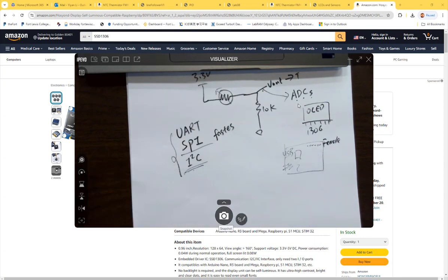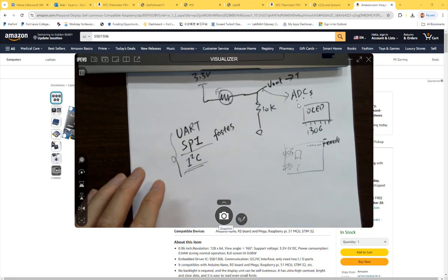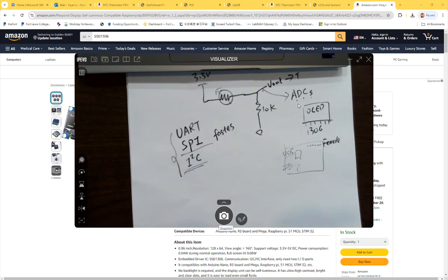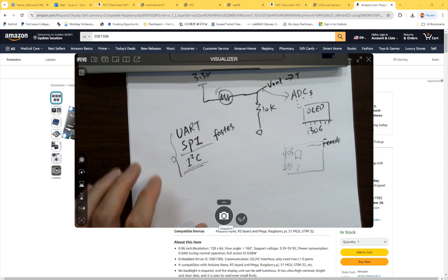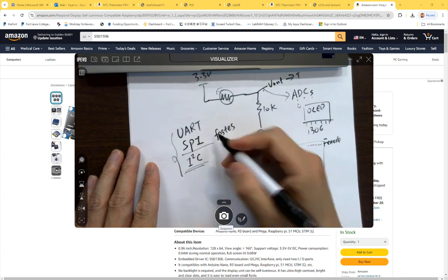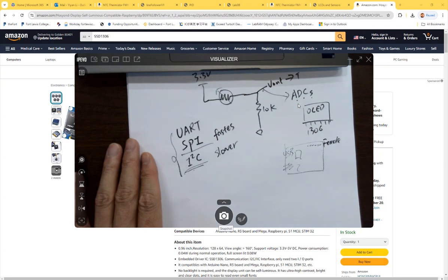You can adjust the speed by changing that pull-up resistor value. You can adjust the speed by writing to the registers to control it. With different speed, you need a little bit different values of the pull-up resistor, ranging from like 5K to 20K, I think. So why sometimes do you need a faster one, and sometimes a slower one? Sometimes slow is good enough. Yeah, that's good. Depending on the medium that you're transmitting over.